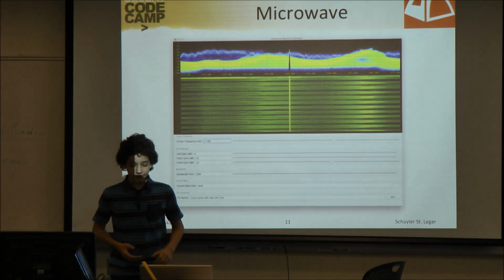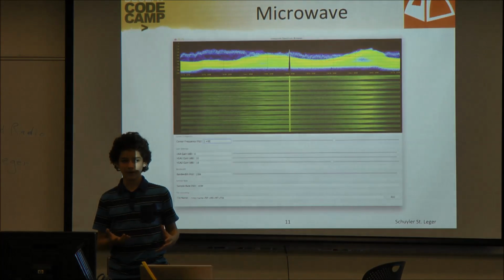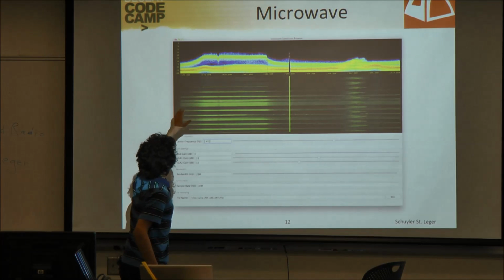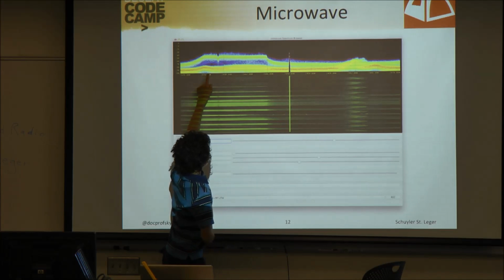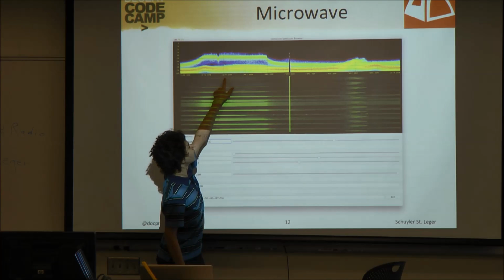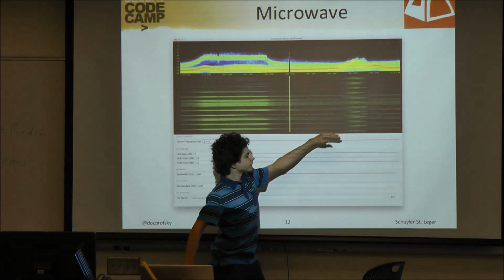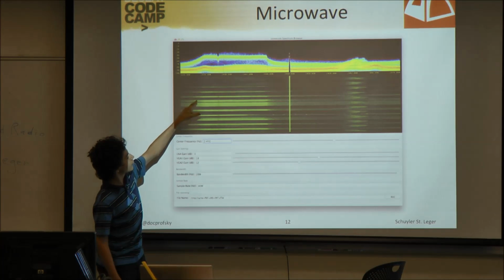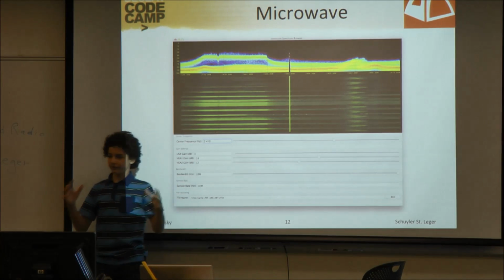But yeah. And then, do all of you know that microwaves and Wi-Fi routers don't mix well? Okay, good. So this is actually a screenshot of the microwave here. You can see the microwave is running, but this is also Wi-Fi data here. This is that same channel, channel 6, at 2.438 gigahertz. And then here's the microwave. You can see the microwave transmits these bursts of stuff. Again, I'm pretty close to the router, so the signal looks stronger. But if your router is next to the microwave, you'll get a few issues.